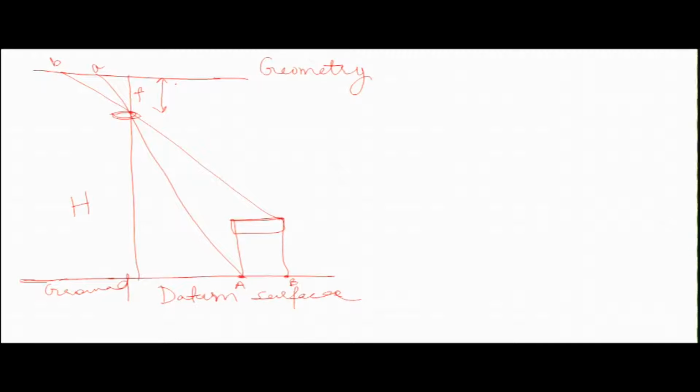So what you can do, suppose the height of this building is h, this is over ground, okay. So this capital D represents the coverage of this building over ground. So this will be small d here from point A to B, okay. So this capital D is represented by the small d on the photograph.